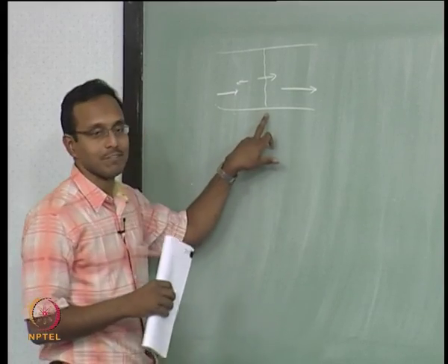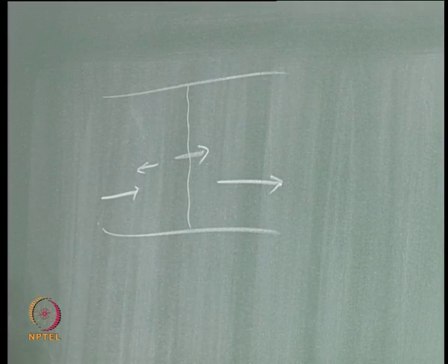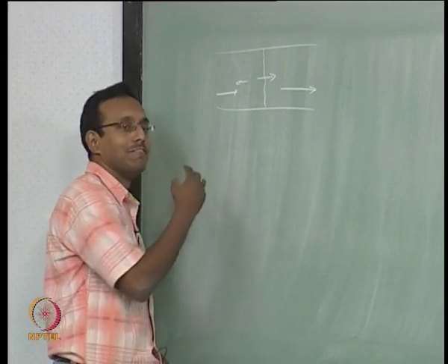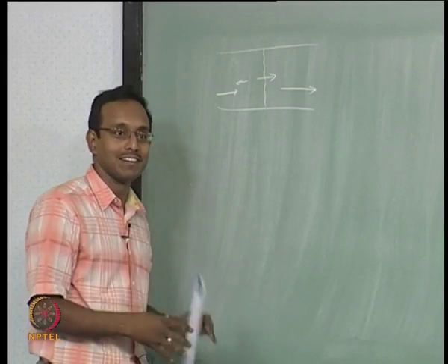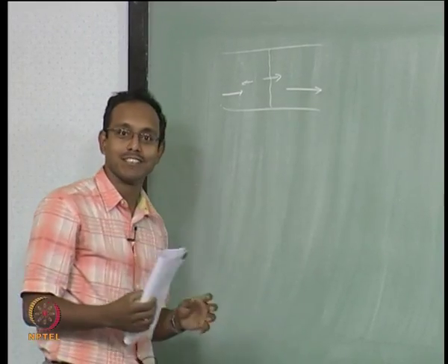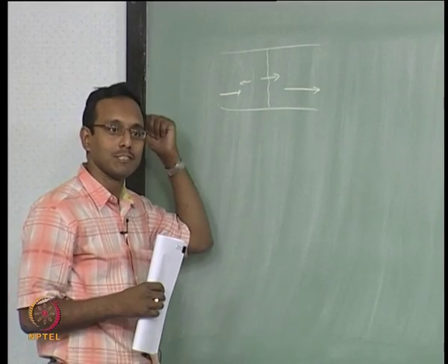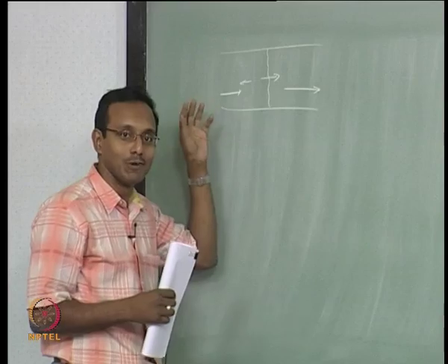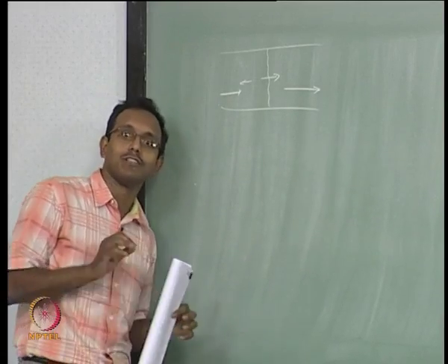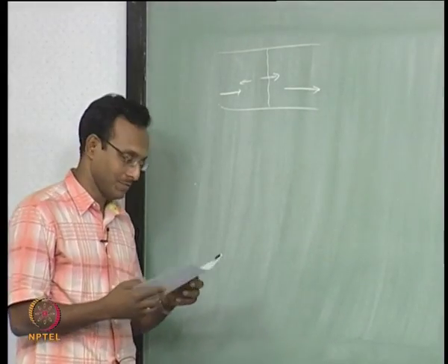If it is an expansion wave, the induced velocity will be opposite. If it is a compression wave, then the induced velocity will be in the same direction. And I gave some statements like the wave will talk to the fluid and it will tell that there is empty space there, go that side, and it will keep going this side. That is what I said last class, right? And similarly, if it is a compression wave, it will tell there is less space there, come this side, and they will go along with the flow. Along with the wave, the fluid will go along with the wave if it is a compression. If it is expansion, it will go against the wave flow direction.